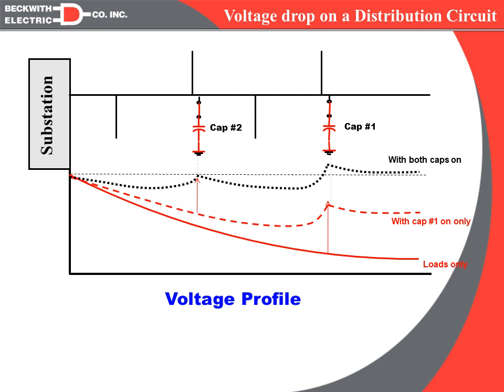And so you can see that, especially where all the load is, on any given circuit, remember that the majority of the current is flowing here, because as customers come off, down below we'll have fewer and fewer load currents, to where when we get at the end of the line, that's where our least amount of load is. And by reducing the voltage, we're going to reduce the load. With that in mind, we really want the voltage to be lowest at the source where all the load is to benefit the most from those savings.